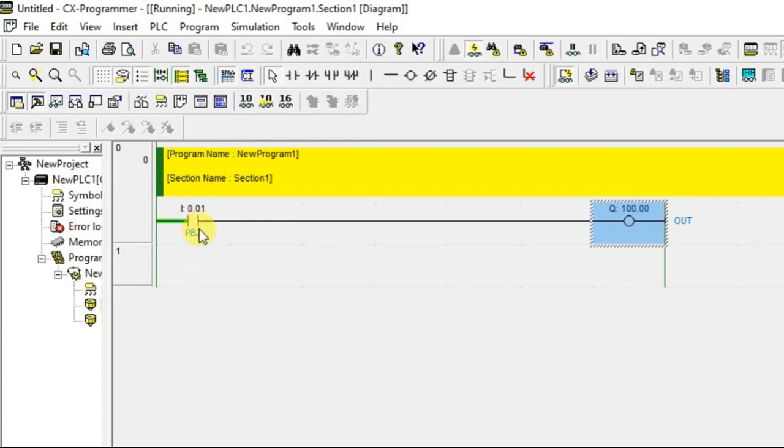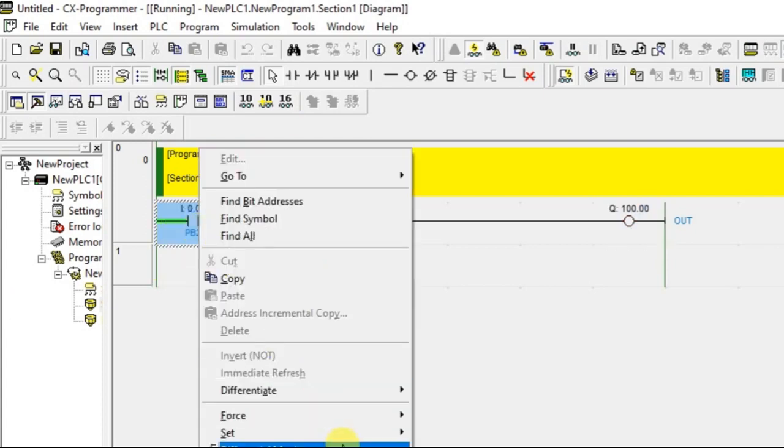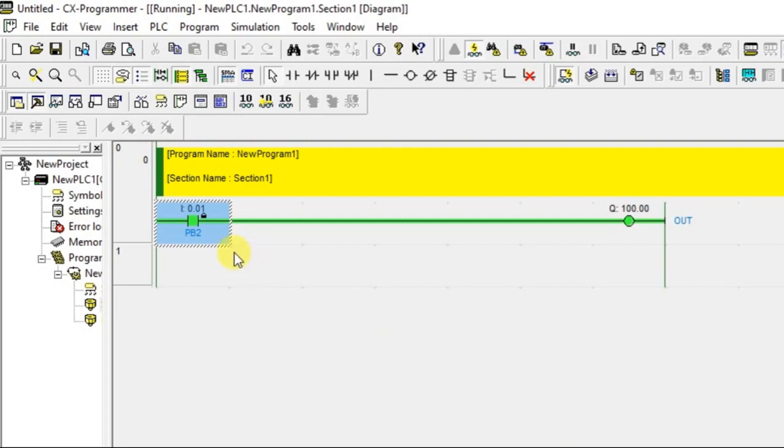Now I'm pushing the push button on and I'm releasing my hand. Output is off. This is how the push button actually works. If you press, it will make contact. If you release, the output is off. But my output has to be in the on condition even though I release the push button, and that concept is called latching. So latching is nothing but making a parallel route.